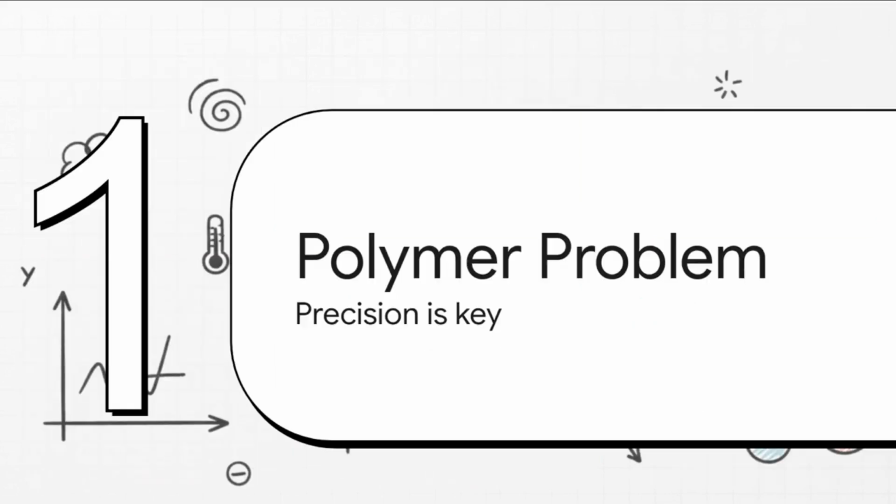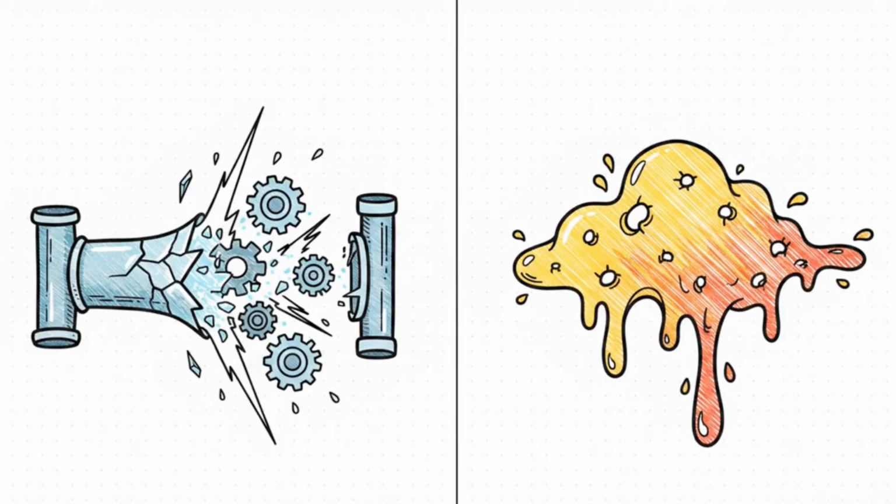All right, section 1, the polymer extrusion problem. The crucial thing to understand here is that for semi-crystalline engineering polymers, like LLDPE, which is Linear Low-Density Polyethylene, the temperature window is incredibly tight. Process stability relies on an exact, spatially varying temperature profile spread across a tool steel processing barrel.